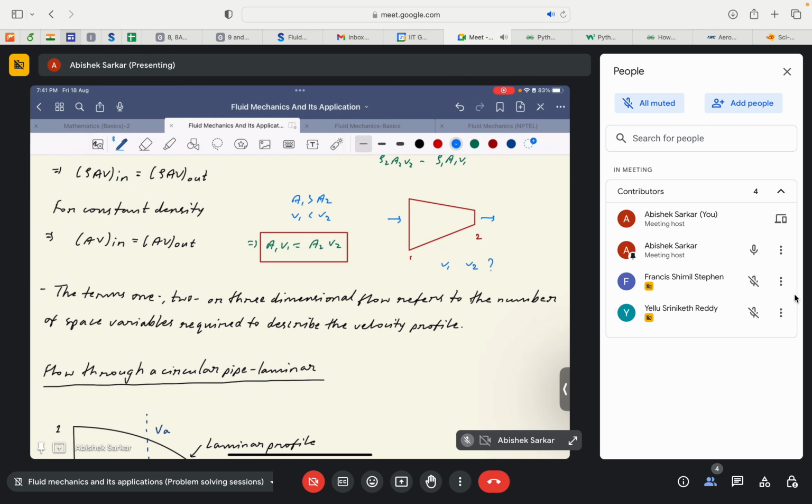But even then, with a simplified version of the mass conservation, where we have disregarded the viscous effects, assumed uniform velocity profiles, disregarded the change in density from cross section to cross section, and assumed incompressible flow, we get an idea that if the area at the outlet is lesser than the area at the inlet, for a steady flow we would have a higher velocity at the outlet. And this is exactly what we see in our day-to-day life.